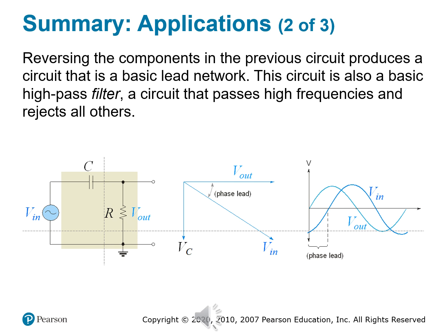So this is a pretty good tool when you want to eliminate low frequency noise, pass along sharp transients, because sharp transients are usually in higher frequencies, or detect fast changing inputs. Again, let's compare this back to the similar inductive circuit, and it should sound familiar. We saw the same high pass behavior in series RL circuits when the inductor was placed before the resistor. But in both cases, you're leveraging reactance's frequency dependency. It just happens in reverse for capacitors and inductors.